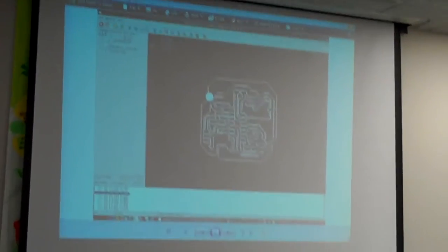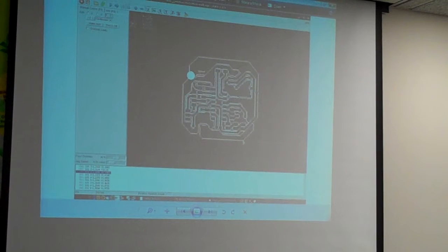So what I see when I go downstairs is the control screen for Linux CNC, or EMC as it's called, where it shows me my part. It shows me the current location of the cutting head. That's what this circle is. And then it shows me it running through all the G-code. And this will just fly by at light speed. It's like every little micro step it takes is a line of G-code. So you'll see that just flying by. And then you'll see in real time the tool moving on the screen.